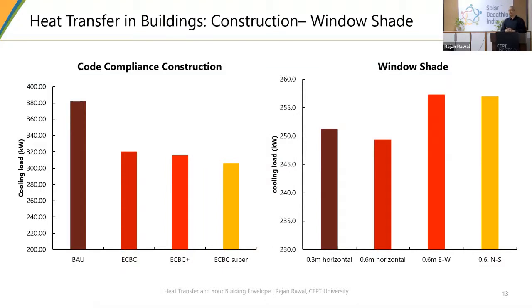When you are going to look at the net zero building, this is where you need to find a sweet spot, because I think the competition also requires you to show a certain kind of cost benefit analysis. Will you really go for super high performance glass or high performance window, or rather super ECBC at 3 times more cost? But it may save a little bit of energy as compared to ECBC. So you might need to look at where the sweet spot is between energy saving and cost, and now also renewable energy generation. This is where such kind of analysis might help you.